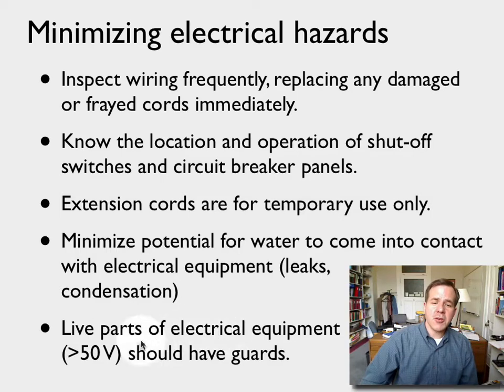Any live part of an electrical equipment which is at any significant voltage, say above about 50 volts or so, should have guards on it so that someone cannot come in contact inadvertently with that potential.